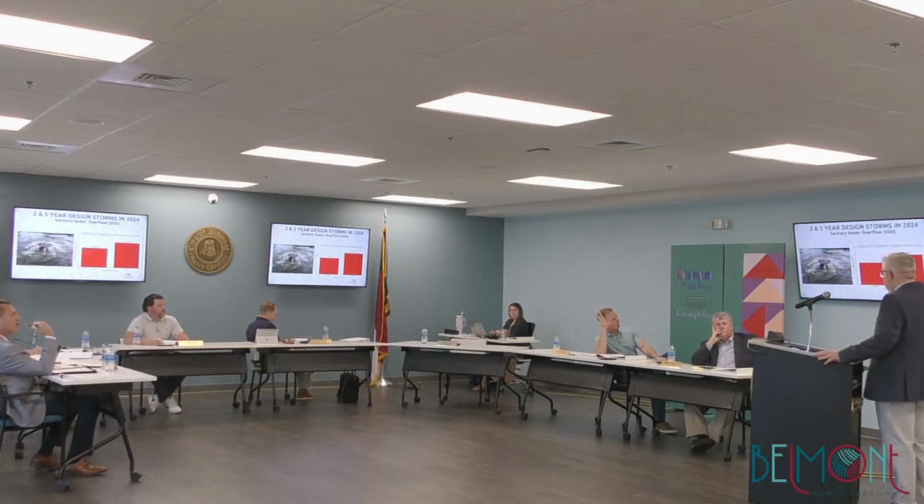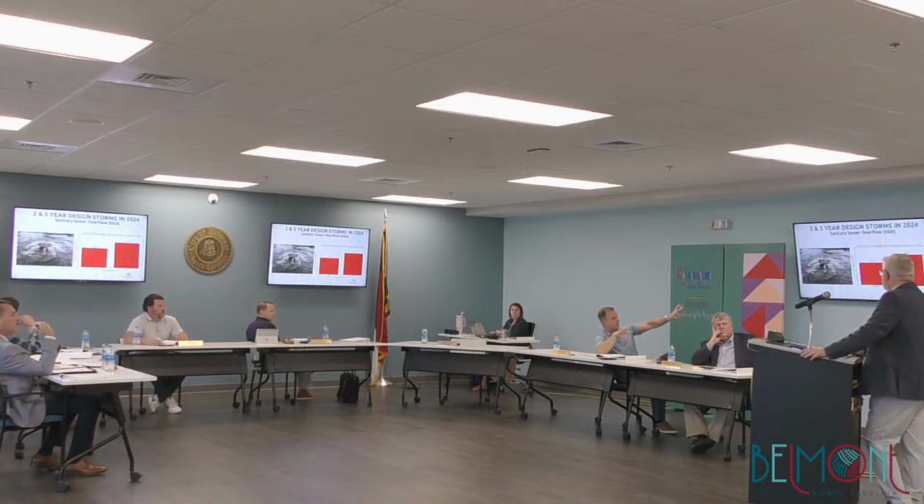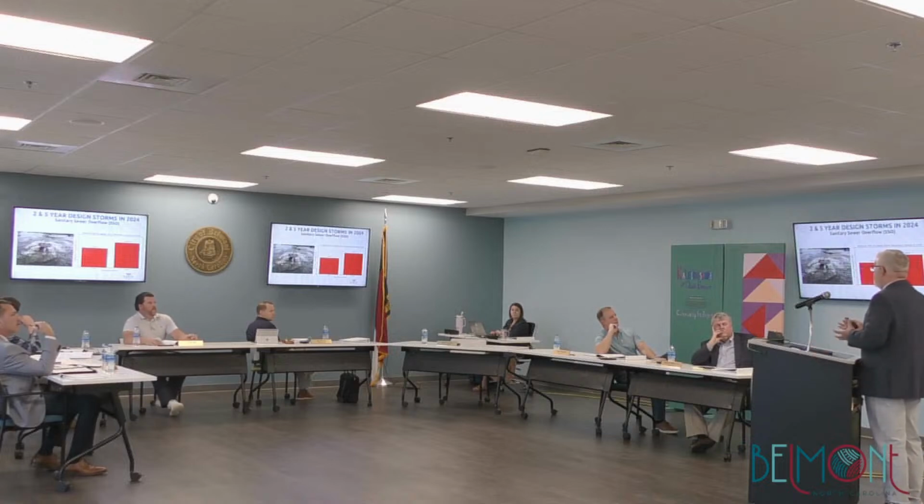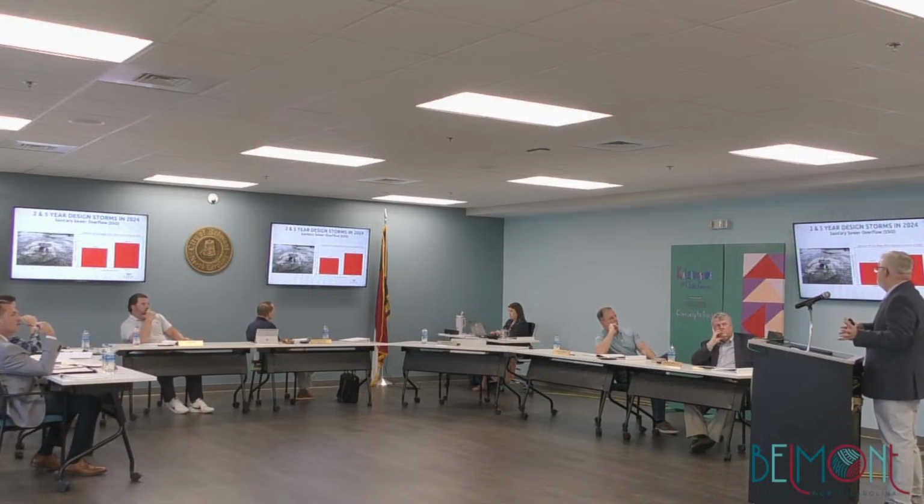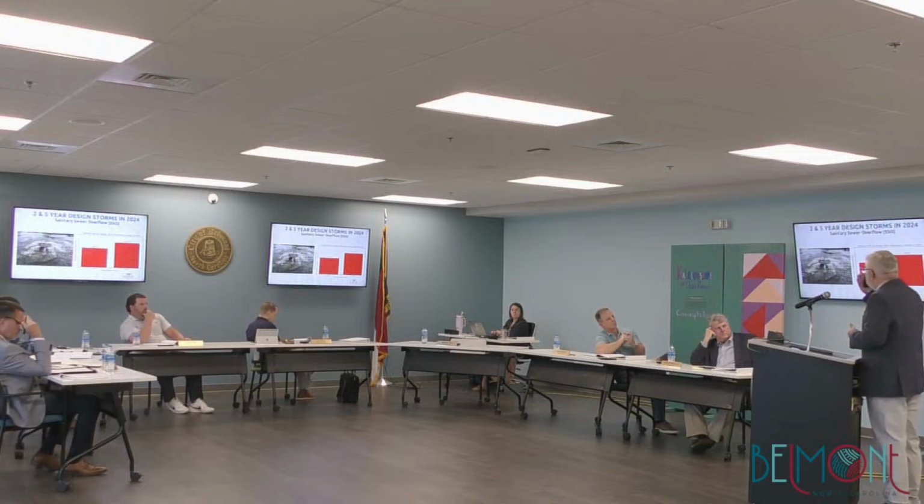Are you saying for a hurricane level storm, that's kind of an outlier and you carve that out of these types of data? Yeah, we carved that out of that data, right? We actually modeled it, and we modeled it because what we want to see is, does that digital twin replicate what we actually witnessed during that storm event? That's what we did here. That's part of that calibration process. And so what that means ultimately on that hydraulic model is that we have a high level of confidence in its predictability.